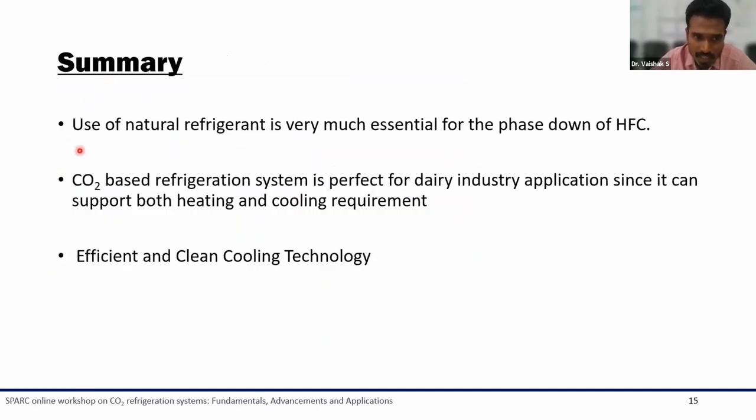So I'm summarizing the presentation here. The use of natural refrigerants is very much essential for the phase down of these HFCs, and in that, CO2 is a good potential alternative refrigerant. And this CO2 finds a very good application in dairy because it can meet both heating and cooling requirements. So we are working towards an efficient and clean cooling technology.